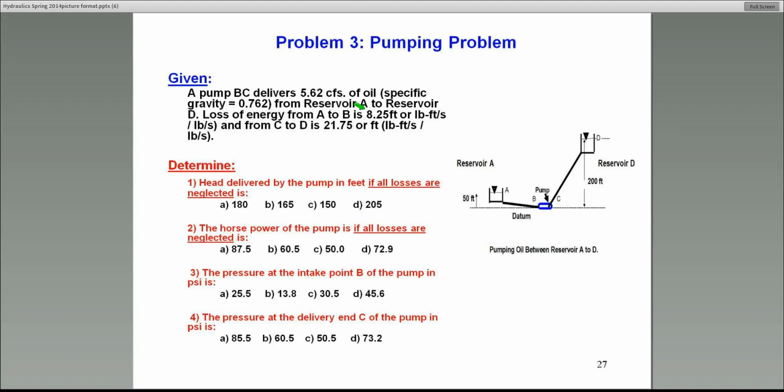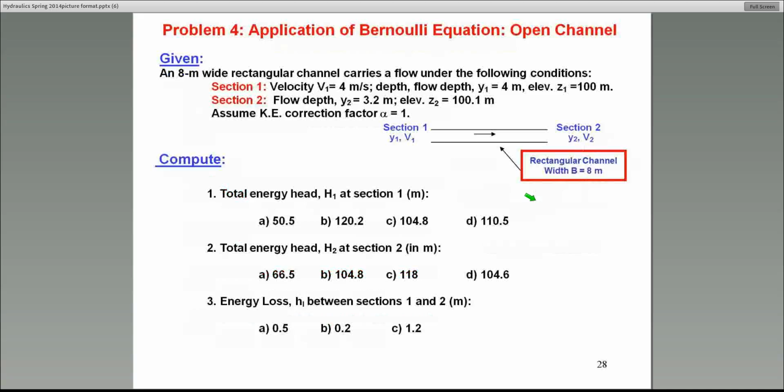By the way, when it comes to pumps, there's a process called cavitation of pumps. That will not happen in this system because the gauge pressure will be positive here. Usually that's an issue or concern if that pressure there drops below the vapor pressure of water. I won't get into that. That's maybe an advanced topic for the morning session. But if you want to know about it, you can always read a little bit on pumps or pump hydraulics.